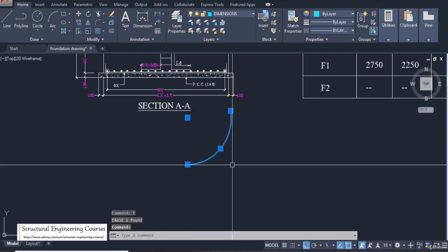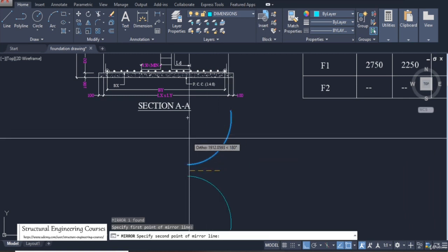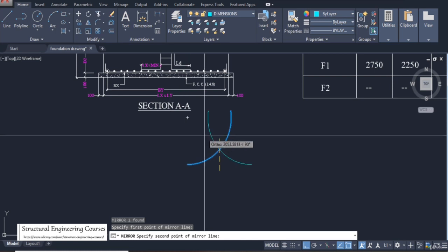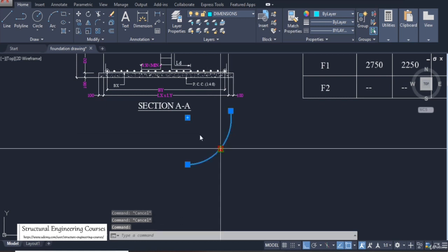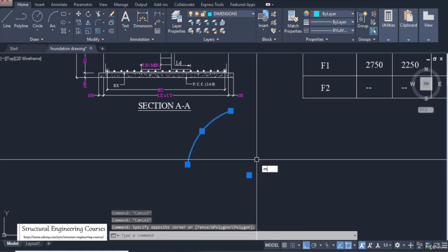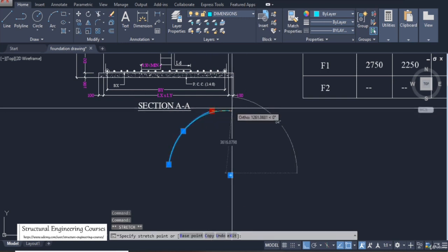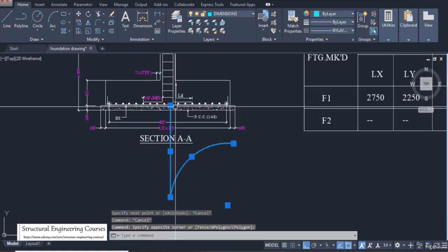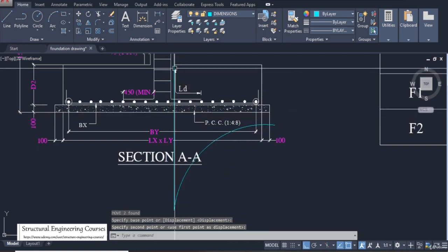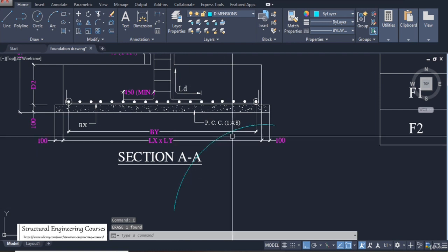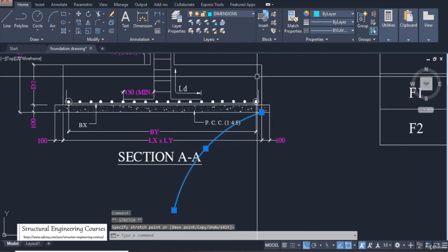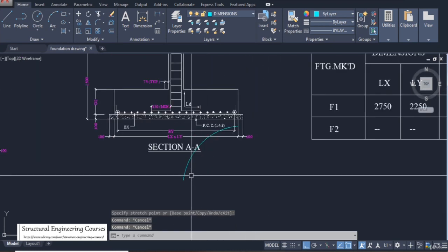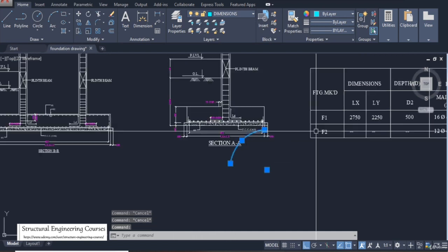The bending moment profile below the isolated footing is in this profile: at this particular point, that is at the face of the column, the bending moment is at its maximum value, that is WL²/2, and it gets reduced to around 0 at the edge of the foundation, or in some cases it may be some minimum nominal value. So this is basically the profile of the WL²/2 here.